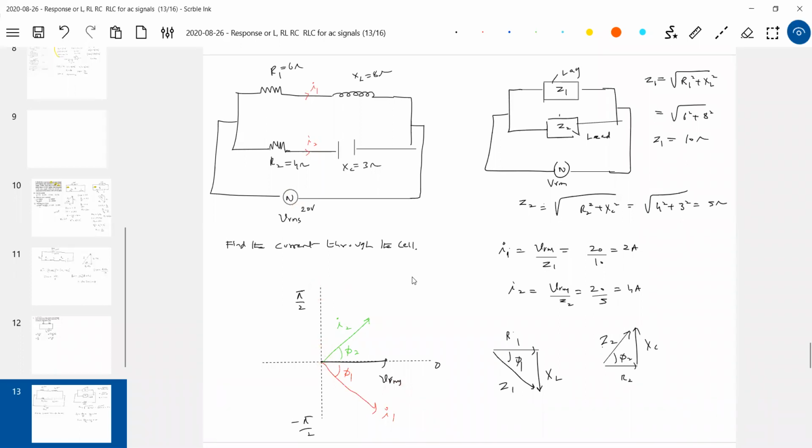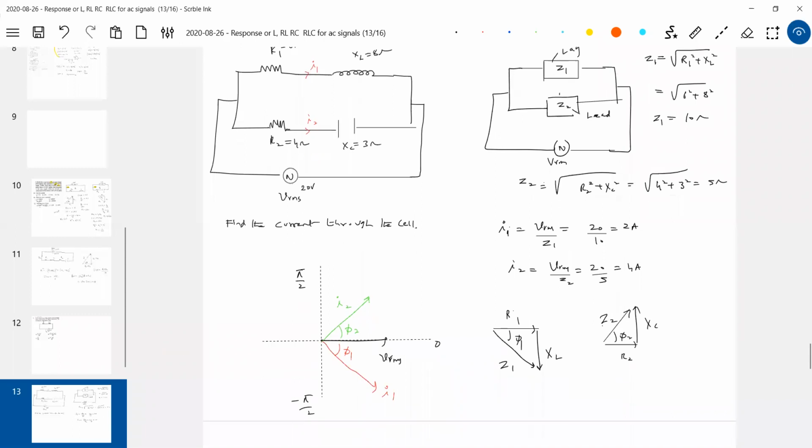This is a much easier approach. Take this to be 0 phase. In parallel circuits, always assume the phase of the source to be 0. If the phase is mentioned separately, then draw the diagram corresponding to that. Since nothing is mentioned, the phase of the cell should be 0 for parallel circuits, I'm telling. Okay, so now can we calculate the phase angle?